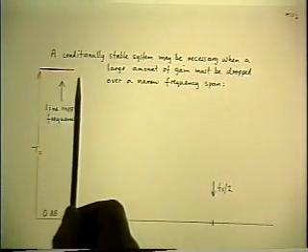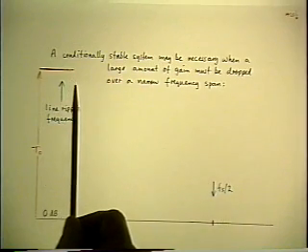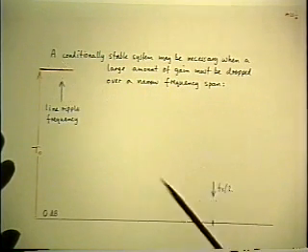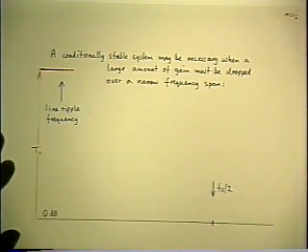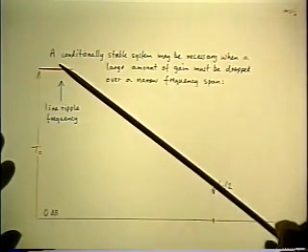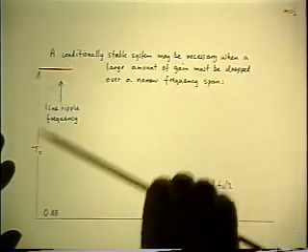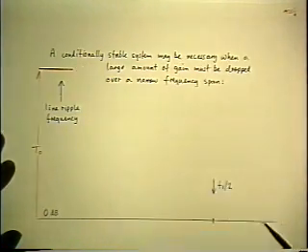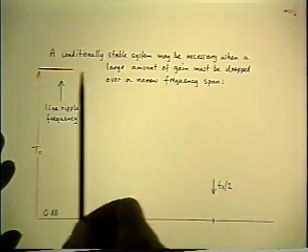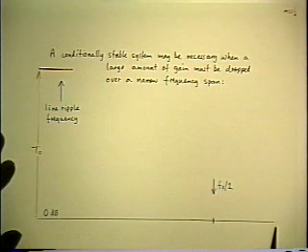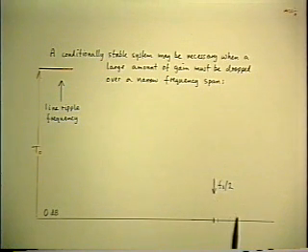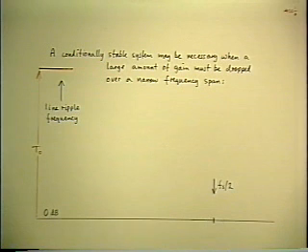Now this gives me a window of frequency in order for the loop gain to go away. It's going to go to 0 ultimately. But if I put a single pole starting at 20 kilohertz and I have to throw away 40 dB of feedback, which is a factor of 100, then the crossover frequency on a single slope is going to be 100 times 20 kilohertz, or 2 megahertz. Now, I can't permit that because I'm not going to be able to control the parasitic capacitances all the way up to 2 megahertz.